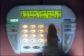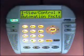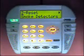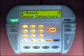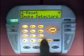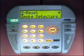The next item, if we press up or 2, would get us to the 2 item. I'll just press the up key. That's reset smoke detectors. In order to reset smoke detectors hooked to the M1, we have a power output that will be turned off for 5 seconds if we enter this reset smoke detector menu.